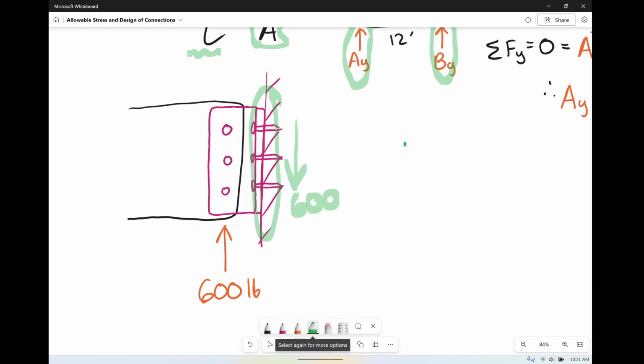So there we go. We have our two things. You can see our shear force is 600 pounds here, and it's going to be applied across these three nails. So if this plate with the nails is stationary and I'm trying to move the beam upward, the only thing that is resisting it are these three nails, and the diameters of those nails are the only things resisting it. So technically we're looking at 3 shear planes. And those 3 shear planes are, of course, the areas of the nails themselves. So the area that is, of course, the shaft of the nail, maybe you want to say it that way.